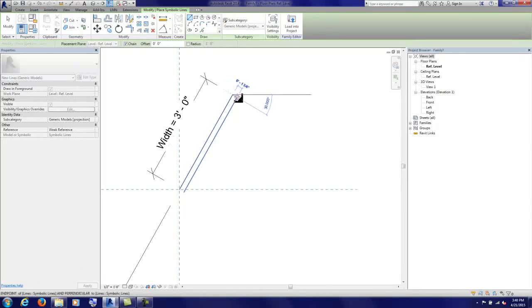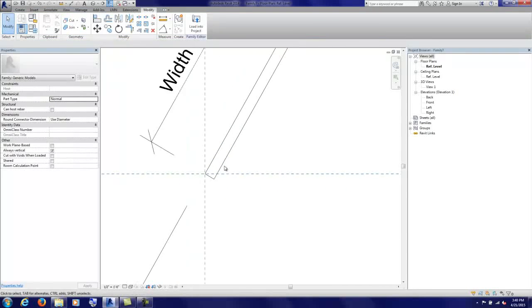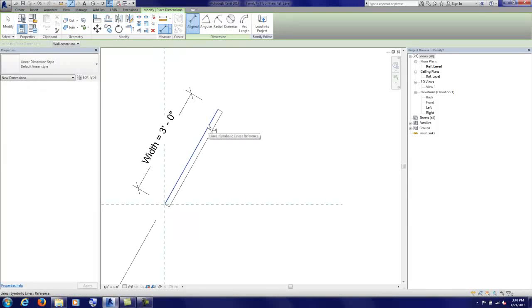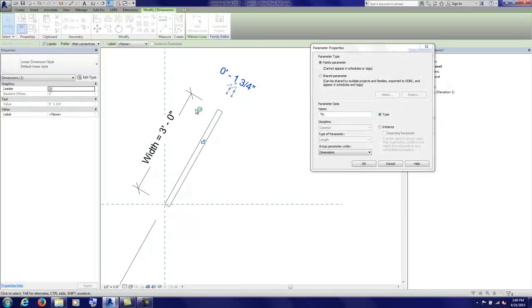want to close the ends of that door panel. And we want to set up dimensions, and it's very important now that we tab over until we find in the lower left corner it says reference lines, reference. It's kind of redundant, but that's what we want to select. And then I'm going to strike a dimension. I'll give that dimension a parameter, and we'll call that thickness. And click OK.